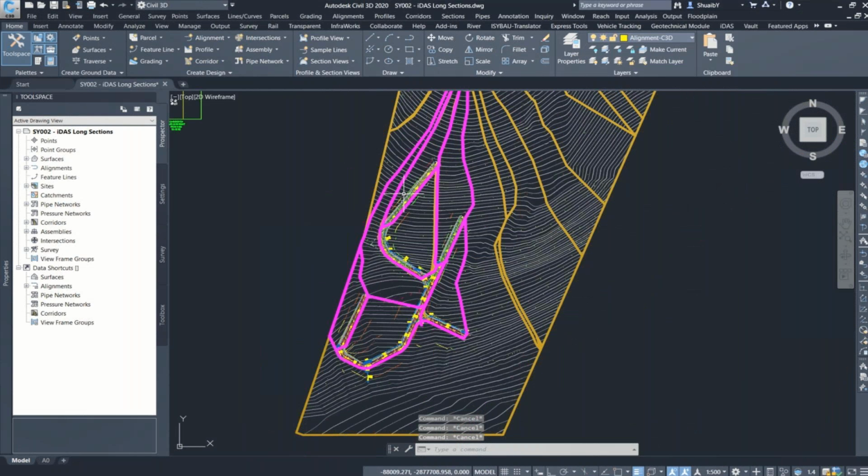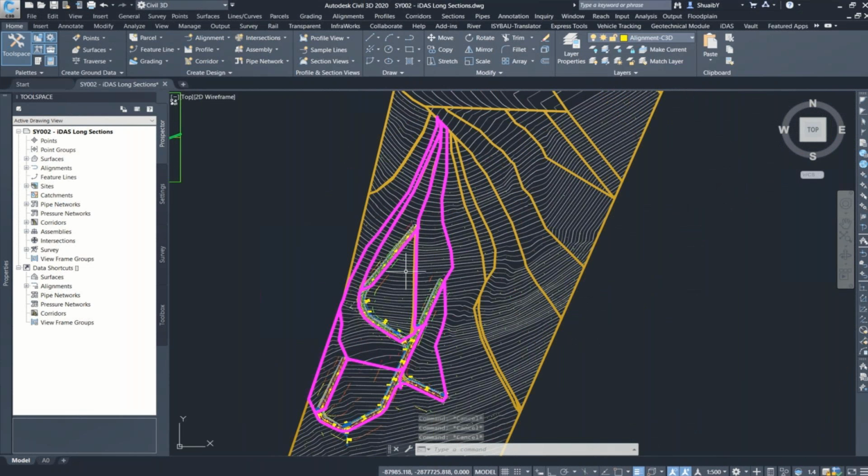I'm going to switch them off because I don't need them, but it gives you a pretty educated, insightful guess. I don't like using the word guess, but you understand what I'm saying. It gives you more insight into your design methodology. And as you can see now, we have all our catchments done for each of our curb inlets. So each one of them has a drainage point. You must have that, else it's pointless if you don't have a flow point in your catchments. That's not practically correct. Okay.